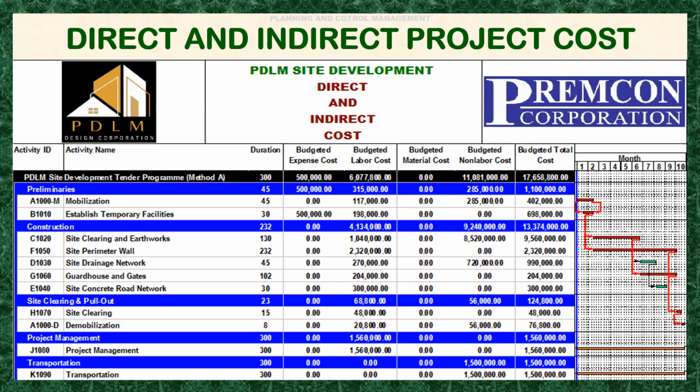And secondly is to derive a formula to calculate total budgeted cost of each activity to include markup cost. And take note also that Primavera P6 global change feature will generate this formula. Okay, let me present to you first the sequence of parameters that we intend to create in the Primavera P6 user-defined field. Then it will be followed by the derivation of formulas for calculating total budgeted cost with markup cost incorporated. So let's do it so that you can visualize what I am saying here.